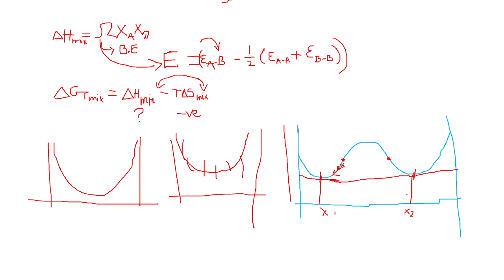Now coming to the diffusional phase transformation. Now, we were at the undercooling part, right? So the nucleation rate will be higher for higher undercoolings, and for diffusion, for example, I'm at T2 temperature, and for diffusion to occur, we need a diffusion of atoms. Again, the diffusion of atoms depends upon the temperature.